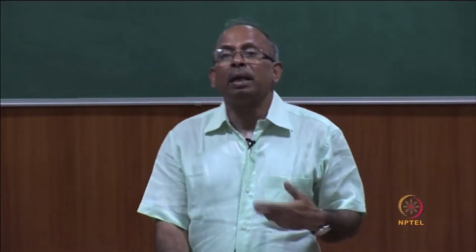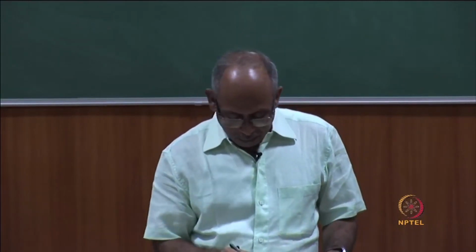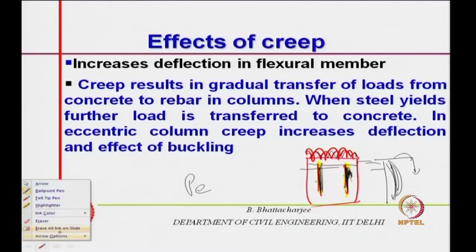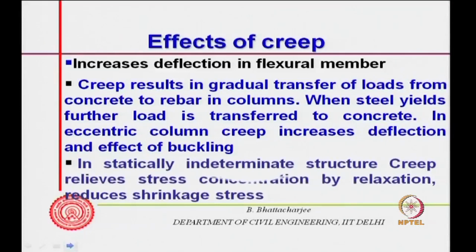And again, the E you take in calculations of all this, the modulus of elasticity, must take account of all these factors. So, this is done while doing design. There is nothing specifically one has got to look into, but the design E must take account of all these aspects in the long run, creep effect and so on and so forth.